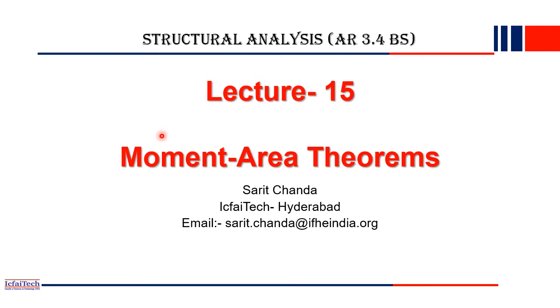Today we'll discuss another method to calculate the deflection and slope in a beam, that is using the moment area theorem. Now you may ask: we already know a method of calculating slope and deflection, so why do we need another method to calculate the same thing? Because in a structure the supports are different. One may be a fixed support, another may be a hinge support, or different support conditions, and different types of loads are acting on a structure. So depending on the situation, one method may be easier to solve. That's why we have to understand a few more methods.